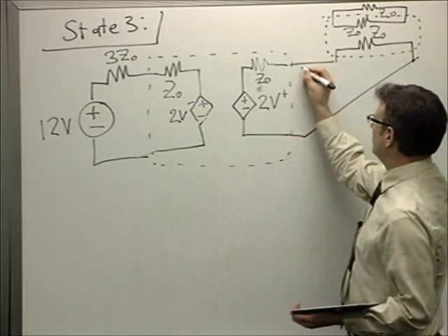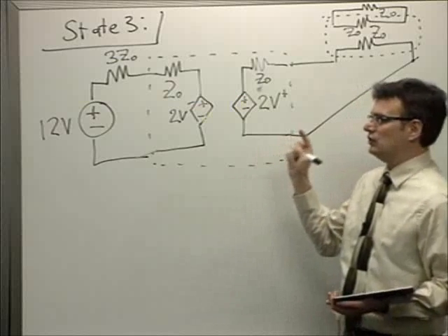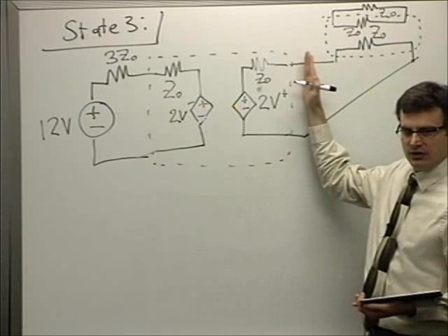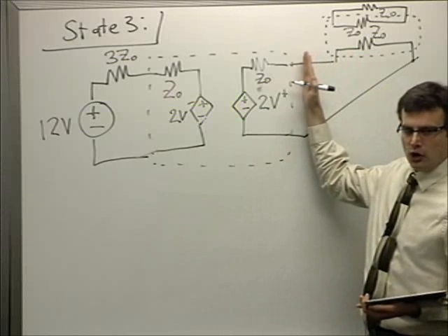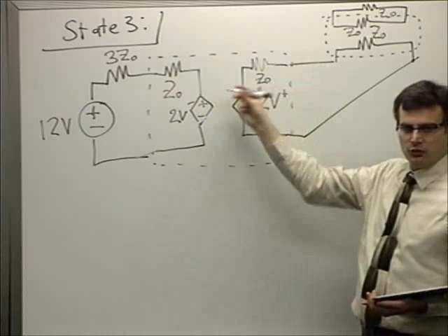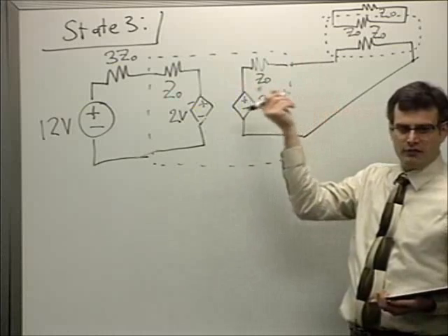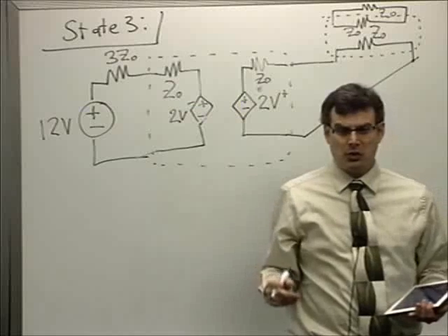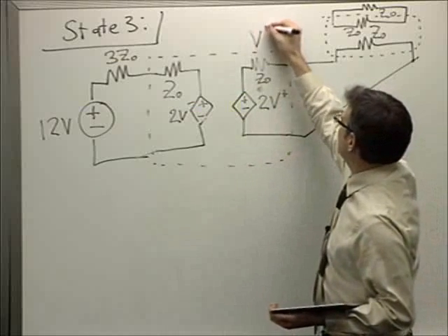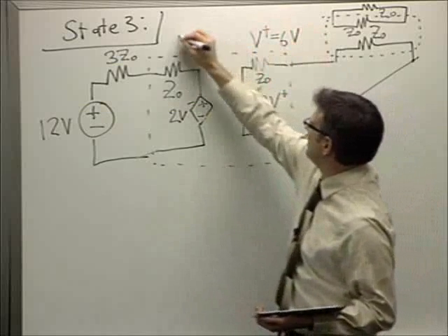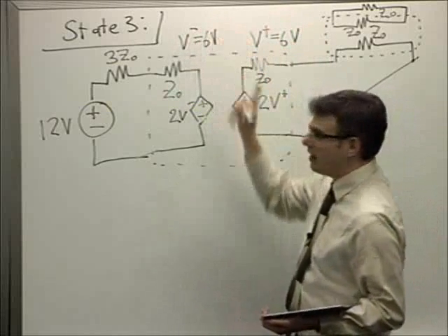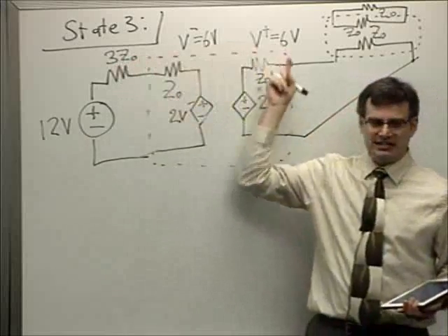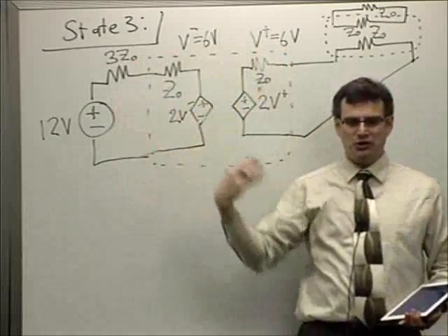Remember, in the previous step, step 2, I had an open circuit before the switch B closed. The reflection coefficient for an open circuit is +1. So I had a voltage waveform coming back. I had the exact same voltage waveform going this way, reflecting back with +1 reflection coefficient. My total voltage were 12 volts. Therefore, I know through common sense that V plus must be equal to 6 volts, and my V minus must be equal to 6 volts. Furthermore, just by making a switch change, these two values don't change, my V minus and my V plus, because these were already put on the line one transit time before.